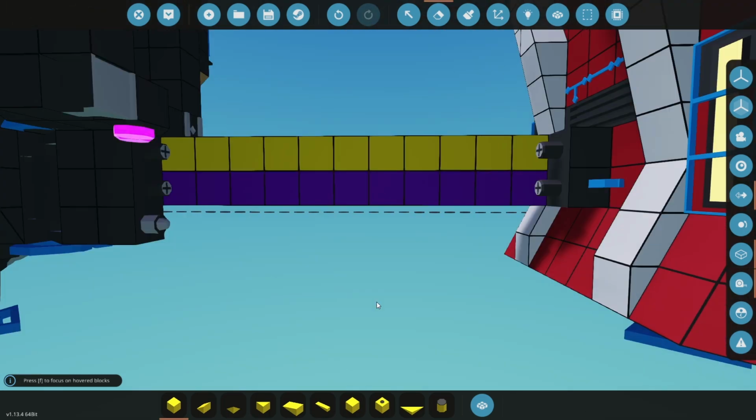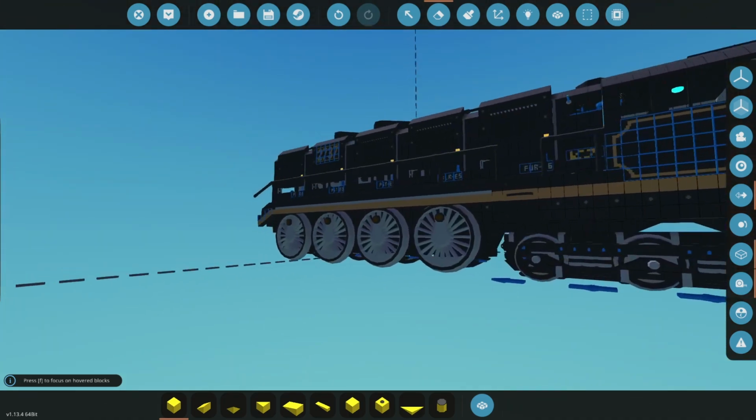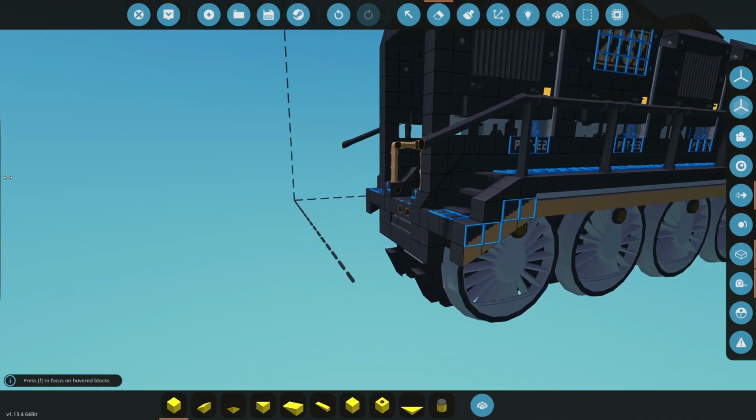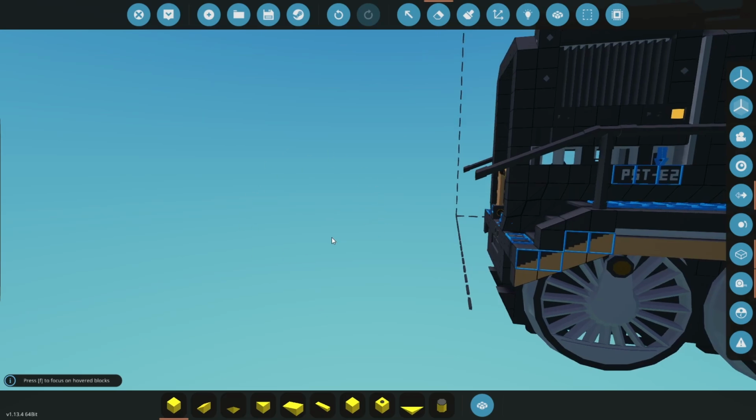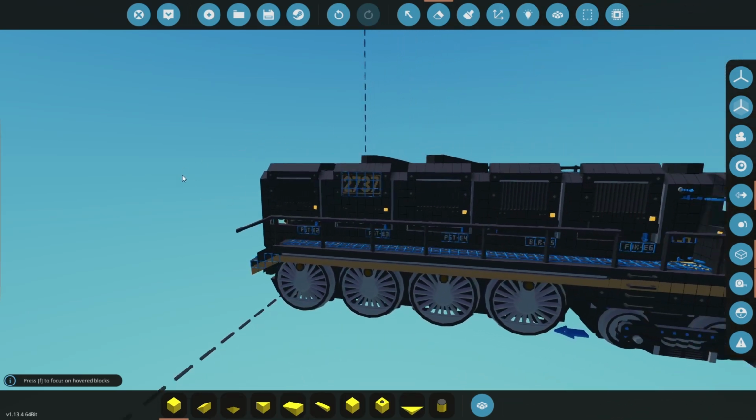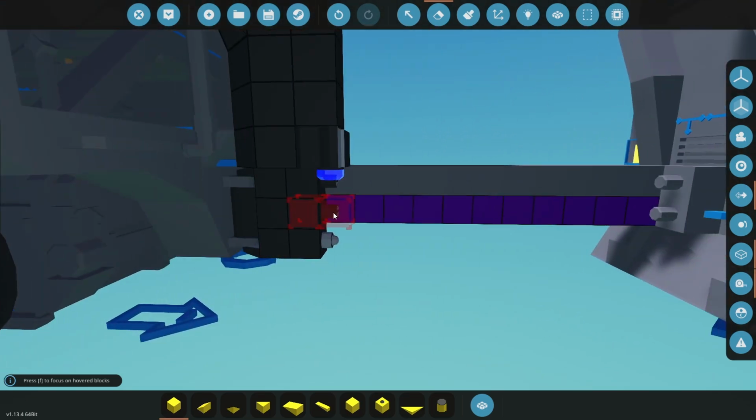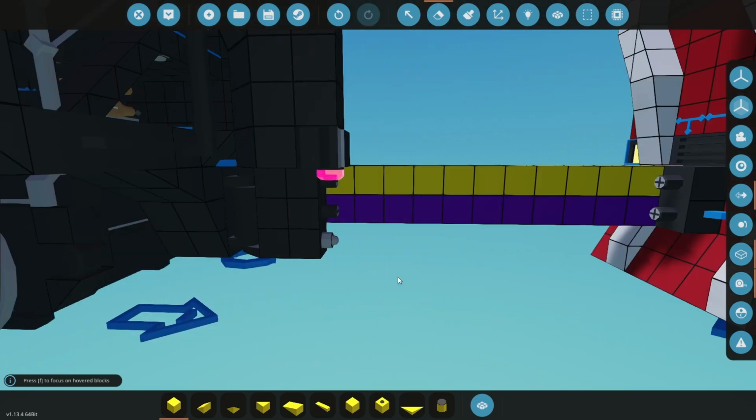Below that is the main TCP connector. So this middle connector is an electrical connector, and that transfers all of the logic from wagon to wagon, locomotive to locomotive, everything. Runs over composite, and it does all your logic. All the logic runs across that. You can plug electricity into this if you want, but it's not supposed to be connected to the main generation system. So it'd be like if you have a side generator. So in the Draken, it's gone now, chopped off. There is a big generator in the front that powers the motors, and there's a small generator up the top. So that small generator could be connected to this middle purple connector, and that will help, that powers lights and things.